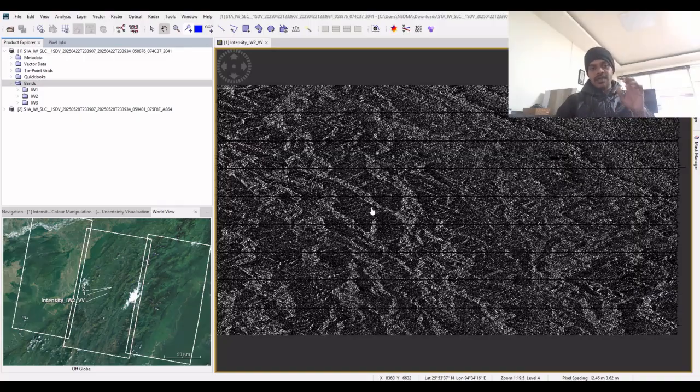This is because when you are applying orbit or doing any kind of interferogram generation, the larger area will take more space, more time and more data. So when you make your area of investigation focused and cut the remaining area out, your processing will be fast, your result will be accurate, and your data will be easy to handle, and you have very little processing time.